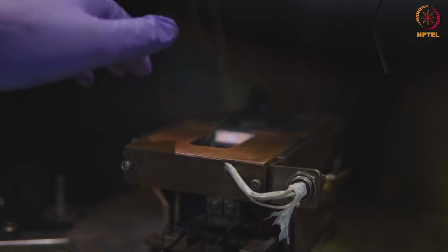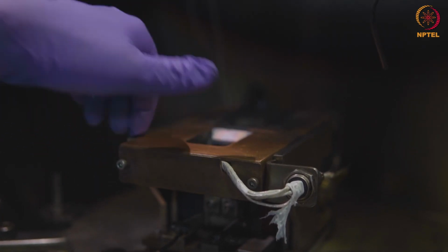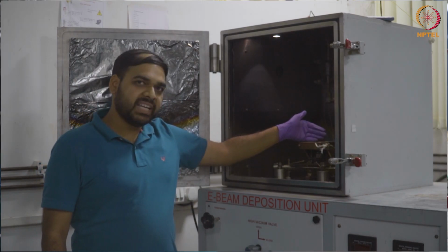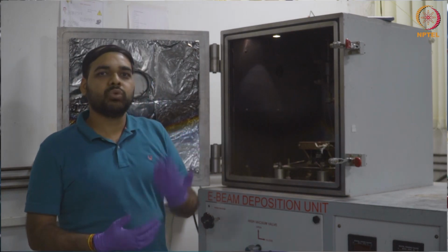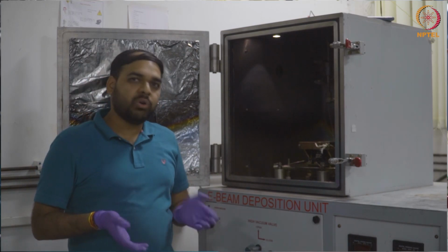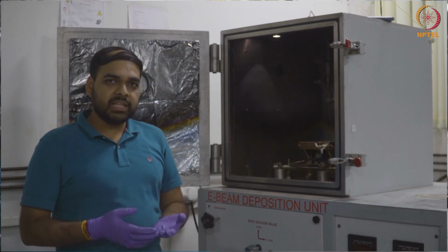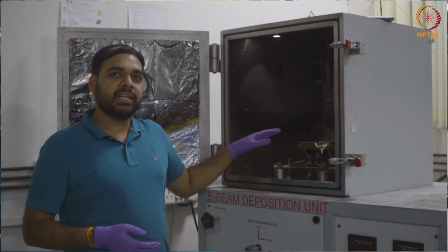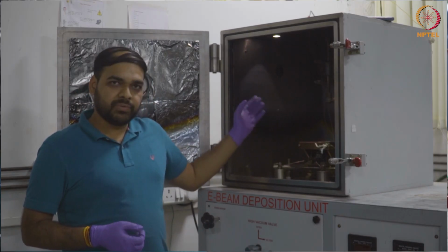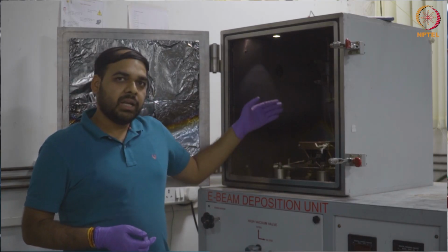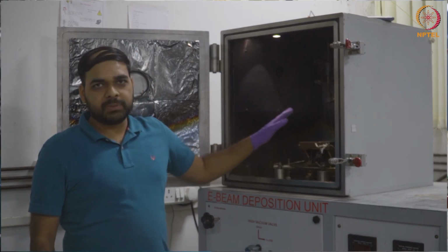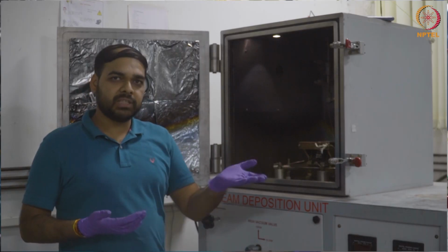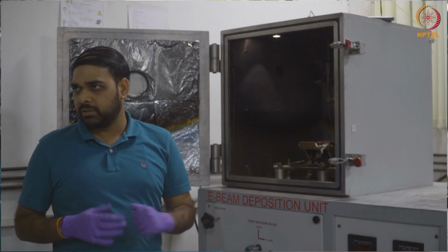As my electron beam goes into that crucible by bending through 270 degrees, it will hit my source material, which can be nickel titanium or nickel titanium copper, or any other shape memory alloy that I want to coat. As it reaches the melting temperature and evaporation temperature of the source material, my material will evaporate and deposit on the substrate, which can be in sheet form or belt form, as we have discussed previously.